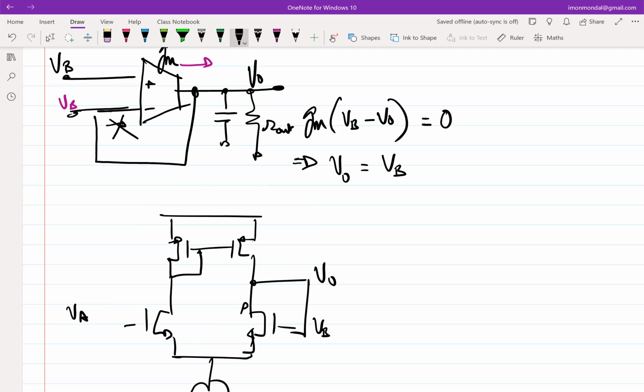Okay. So now let's see who sets it. So approximately V0 will be, quiescent-wise, equal to... let's say I have applied a battery here of value VCM. So V0 will be approximately what? VCM, right? Set by negative feedback. The loop sets the output voltage, right?